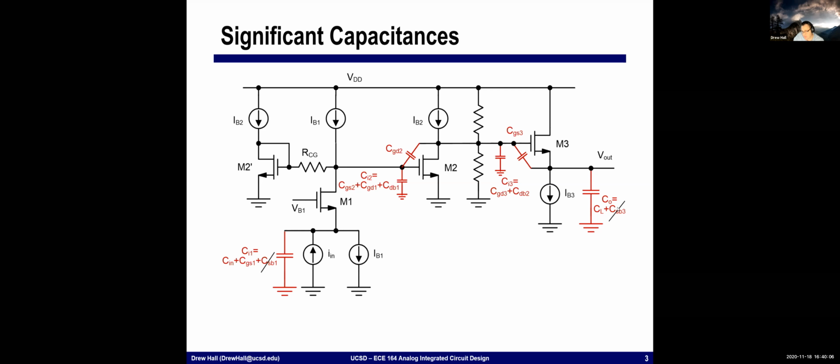And again, given the fixed output capacitance that I already know, I'm going to neglect CSB in my first pass design analysis. I will keep things around at other points for a little bit until I know their relative capacitance. But since I'm given a CL and given a Cin, I think that it's reasonable to make some assumptions about CSB1 and CSB3.